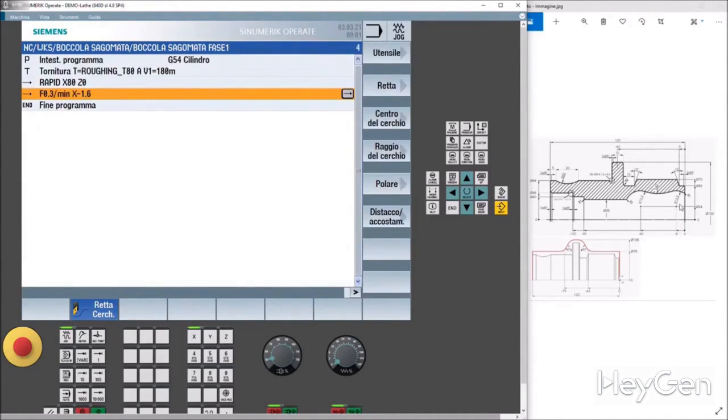If this happens to you, I'm telling you this simply for the sake of record, that when you arrive at the center, the insert breaks. It's due to the fact that you have the tool either slightly low or more likely slightly high. So, it will put pressure on the facing chamfer. Maybe for this discussion, I'll make a video with a 3D.